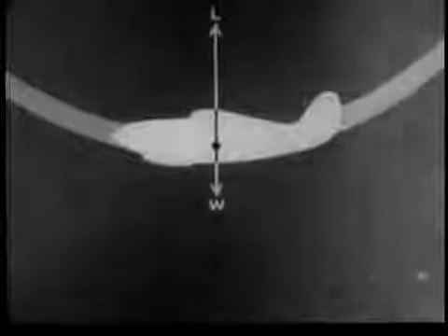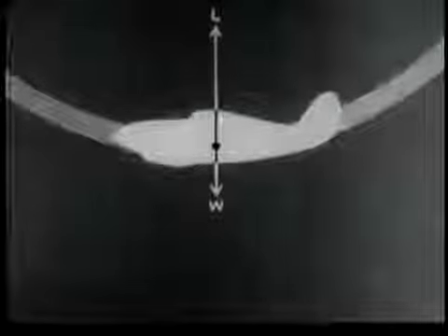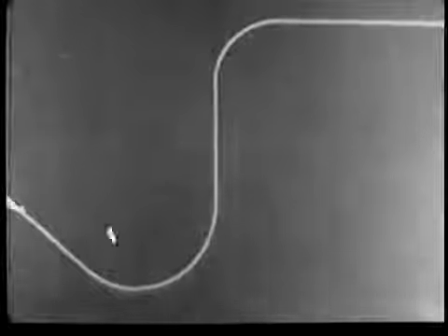In pulling out of the dive, the angle of attack must be increased slowly. During this maneuver, the lift may attain several times the value of the weight. This increase in lift produces acceleration, which in turn produces a curved flight path. Aerodynamic reaction.